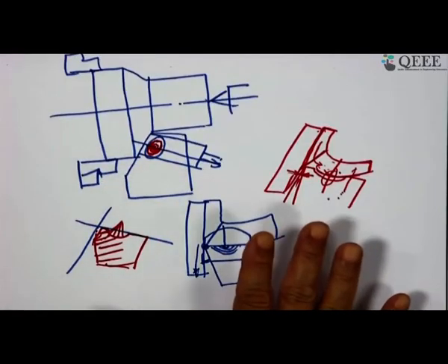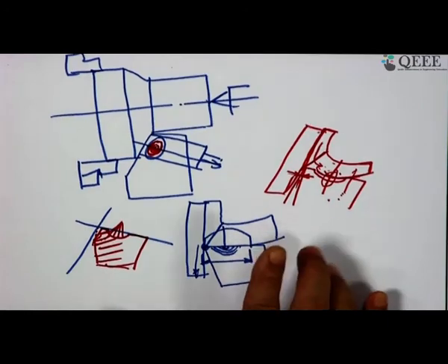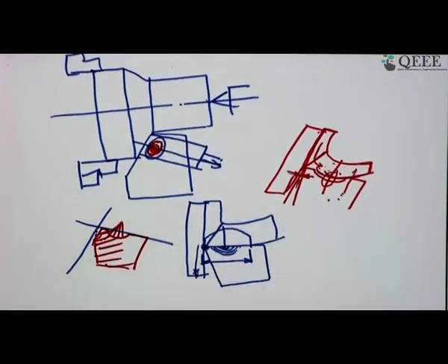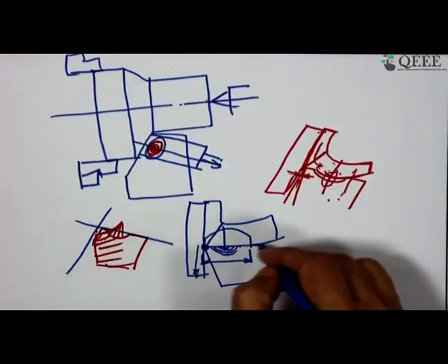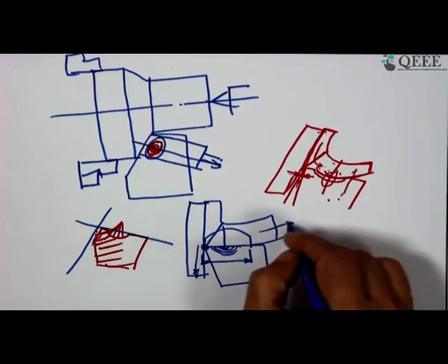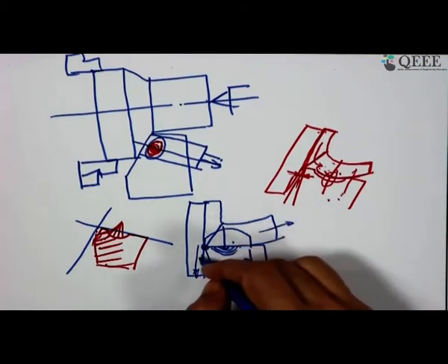Okay, friend, I would say one is the cause and another is the effect. It is not diffusion; basically you have temperature sensitivity. When you take the cutting phenomena in the temperature sensitive zone, again I repeat, it depends upon the selection of these two. I am concentrating our discussion only on the chip side because the temperature is higher there than on the flank.